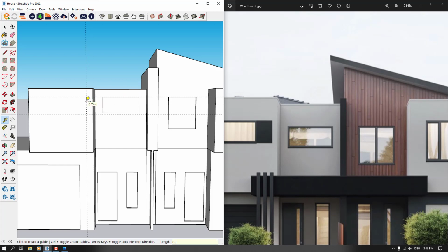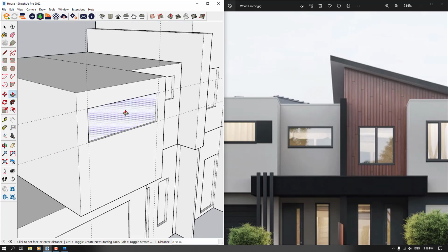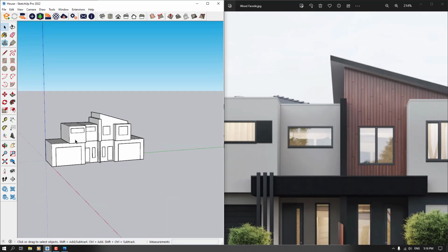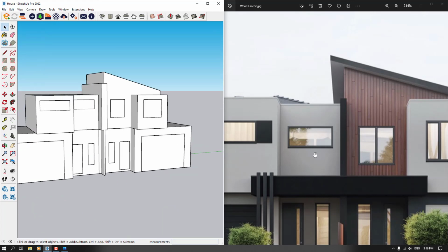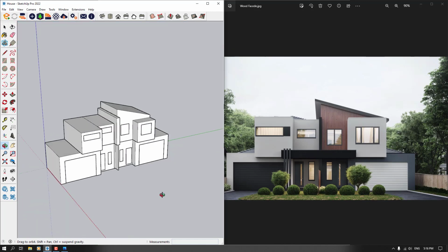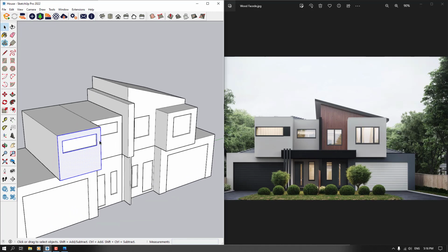A little bit from the right side and 30 centimeter from the left side. I draw my second box in here, push it back about 10 centimeter. Very simple and easy to create these types of shapes only with SketchUp without any objects or subjects. So I'm gonna make this into a group and this one into a group too.